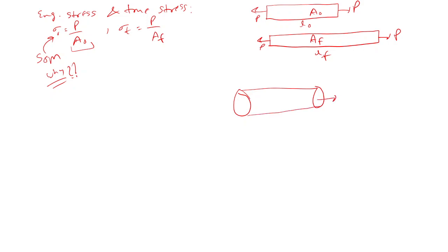Let's suppose this is the beam, and the initial diameter is 80, and the final diameter when load is applied becomes 79. So there is a 1 mm change in the dimension. But if we take the true stress, the calculation would be very difficult, because the diameter keeps changing at every instant. Monitoring that is very difficult, and the calculation would be very tough. The error is also not much, because if the deflection from 80 is 2.44 mm, then with 79 you will get 2.42. That is not that much difference.